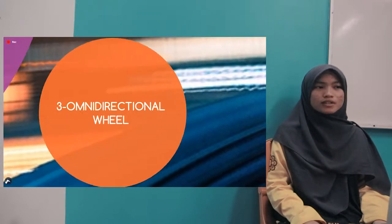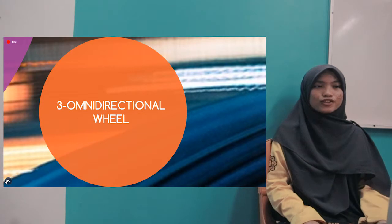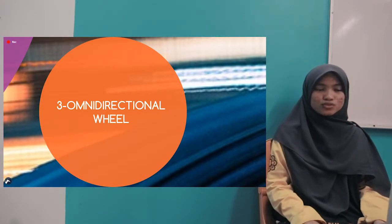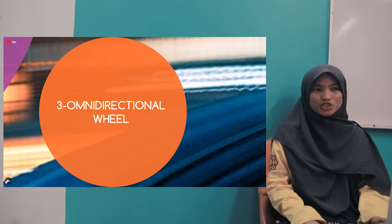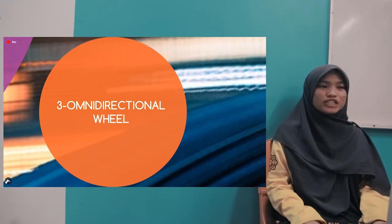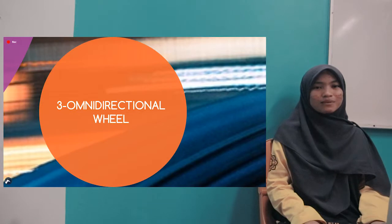For this robot, it will also be driven using a 3 Omni wheels configuration. We decided to use Omni wheels because of their holonomic motion. The robot can move in any trajectory of a plane, and it can change its orientation simultaneously by using Omni wheels.